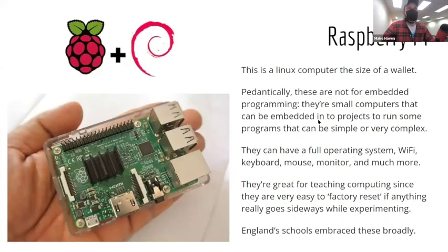Another way that you can do embedded programming is Raspberry Pi, and this is a super fun one. In general, this is different from an Arduino. An Arduino isn't really a full computer. It's just a logic controller, versus the Raspberry Pi is a real legitimate computer. You can log on to Linux, you can go on a web page, you can watch a YouTube video if it's a fast enough Raspberry Pi. All of that is totally available through Raspberry Pi, and they've got tons of cool options. Essentially, I would choose a Raspberry Pi over an Arduino if I need a lot more processing power or if I need to be connected to the internet. The Raspberry Pi is much better at those things.